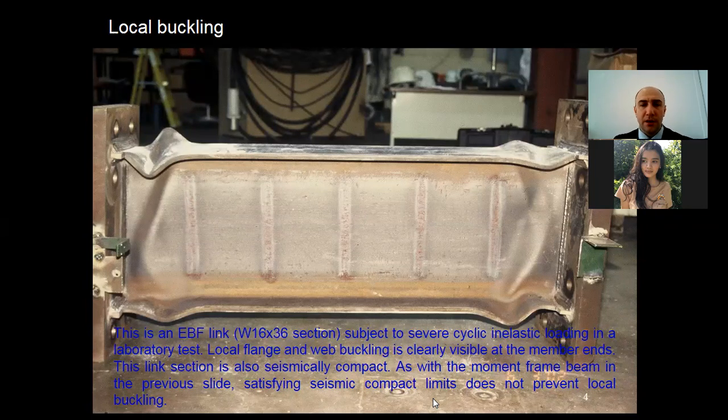The link section is also seismically compact. As with the moment frame beam on the previous slide, satisfying seismic compactness limits does not actually prevent local buckling. Because this link section was seismically compact, it developed very large inelastic deformations before ultimately failing due to local buckling, like you see in the picture of the beam.